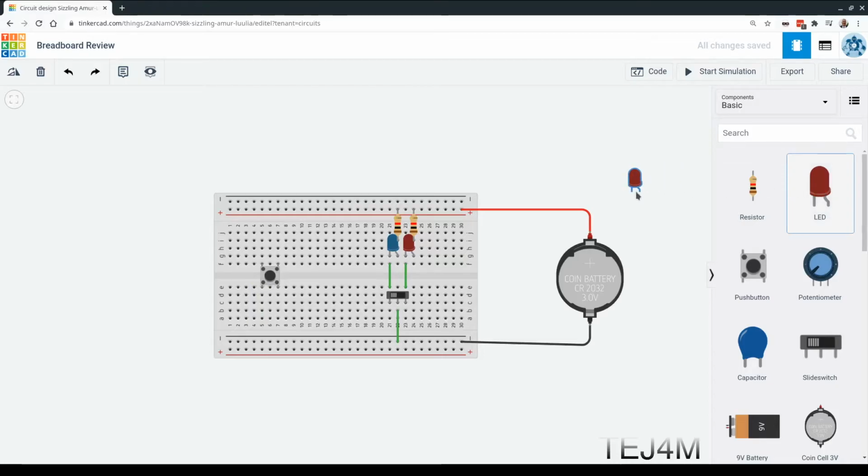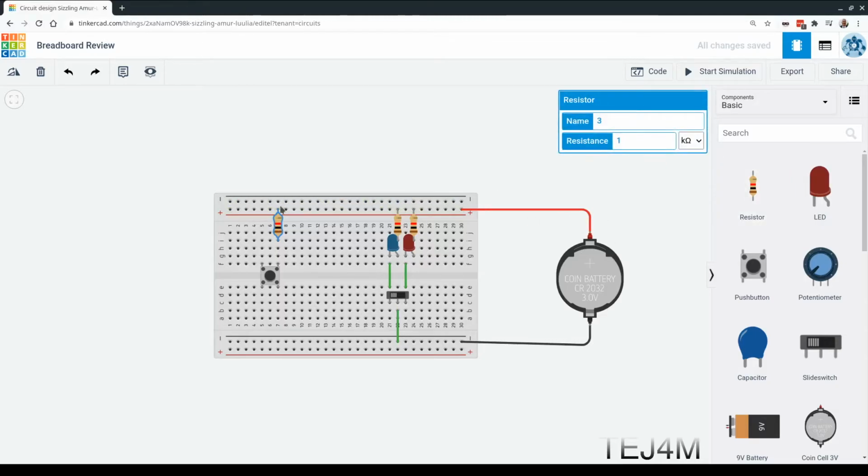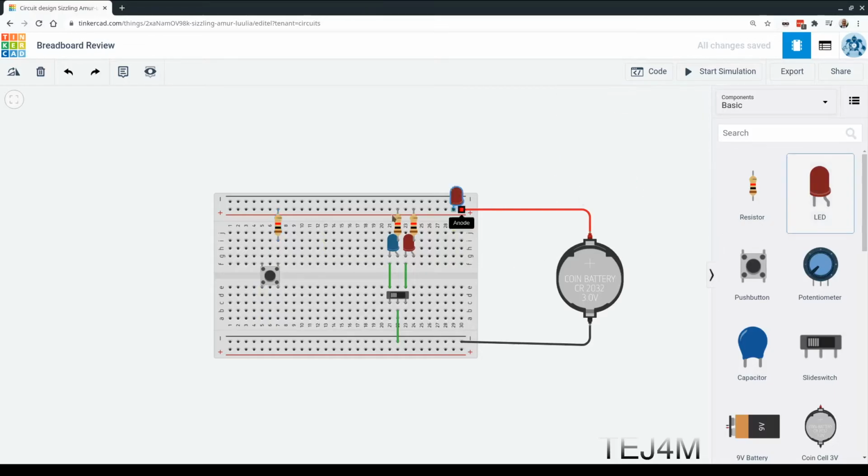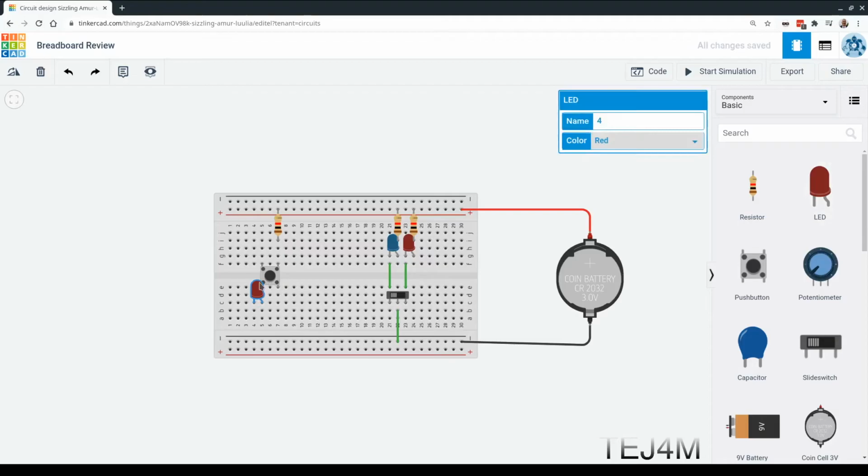We'll put the LED, well, first of all, we need a resistor, right? So we'll have our resistor. It's always a good idea to have the resistor first, just that's kind of the way that I learned it, and that's the way that I'd like you to learn it too. So the resistor goes from the positive bus through this terminal here, and if we push the button down, it'll make a connection across to the diagonal here. So I'm going to put our LED with the longer leg of the LED, the anode, connected to this, I guess it's called terminal 1A. And then we'll have a wire running to our negative or ground bus.